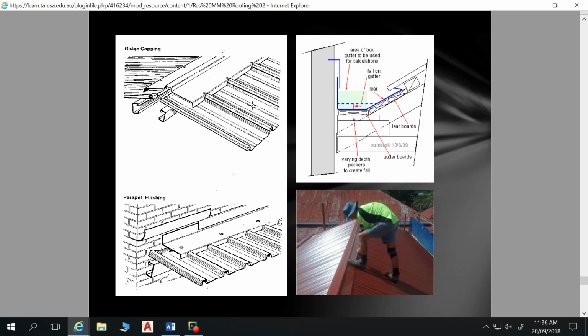Don't worry. But yeah, if you can have your flashing securely fixed and all facing away, making water flow by gravity, it's your better detail. So what we have is our parapet gutter that goes in first. Parapet gutter, box gutter, they do get used interchangeably, but correct terminology is parapet gutter in here, and then our flashing laps over the top of that gutter.